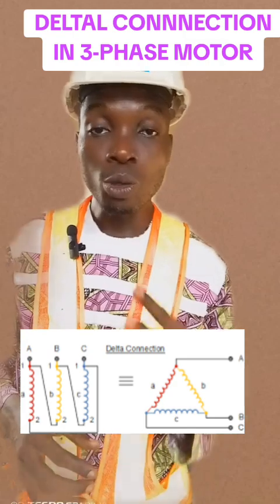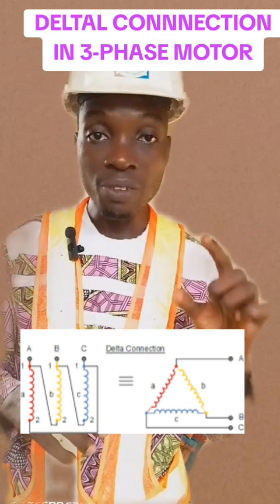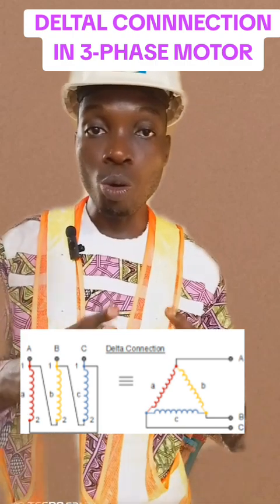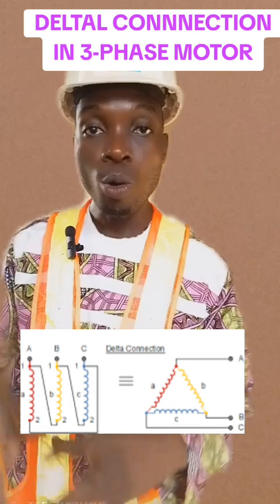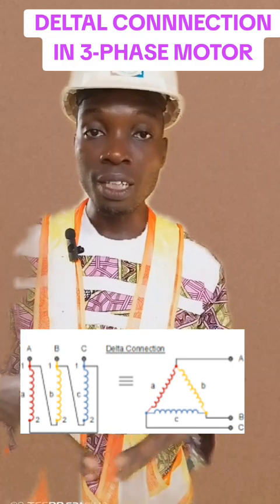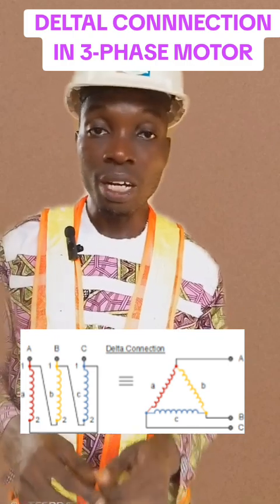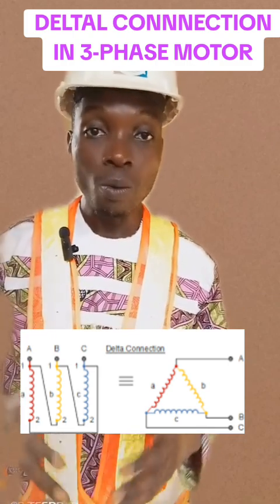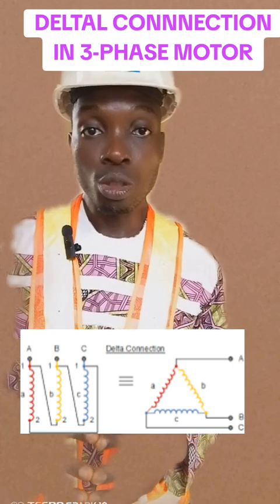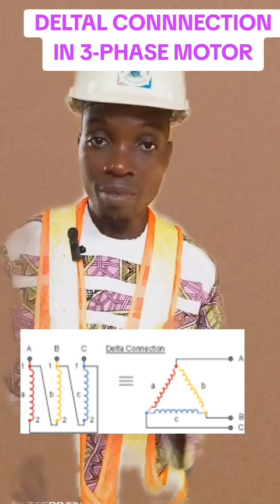Mind you, do not forget that a three-phase motor does not require neutral to run, only the three phases, line 1, line 2, and line 3. But you need to configure it either in Delta or in star before it starts running. So for the purpose of this class, we are going to learn how to connect our three-phase motor in Delta. Just sit back and relax while I take you through both the theoretical and the practical demonstration of the connection of a three-phase motor in Delta.